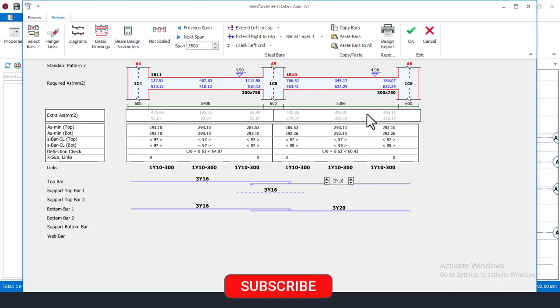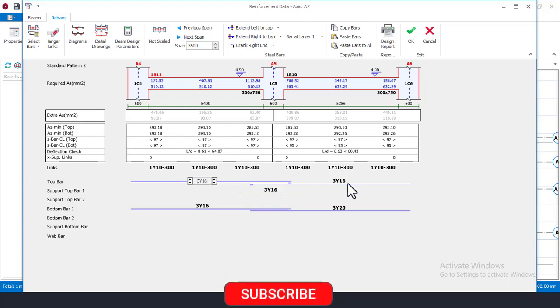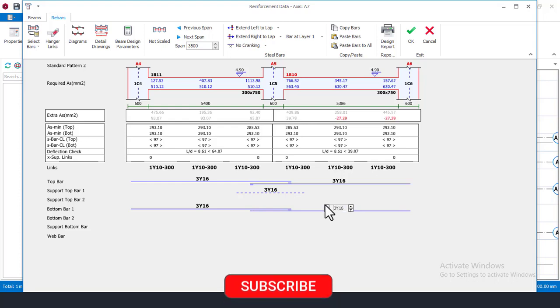But I think right now the 3 at the top is still low, so I can choose to have 4. But I think this is okay. Yeah, this is okay. 3 on this side is still okay. I can see that this top here, the extra area here is okay, and also the deflection is very far away from the limit. So I'll come again right now, reduce this to 4 numbers, and it's fading here. I'll increase to 4 numbers here, and then, sorry, I decrease the size to Y16 and then increase to 4 numbers.